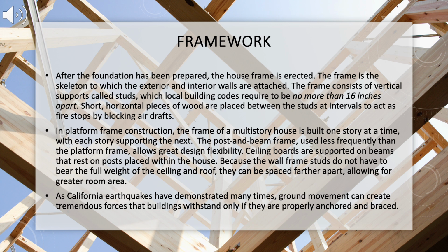In platform frame construction, the frame of a multi-story house is built one story at a time, with each story supporting the next. Figure 14.4 shows the components of a platform frame system.